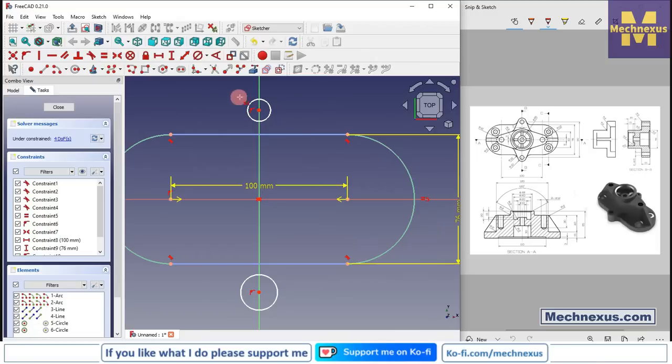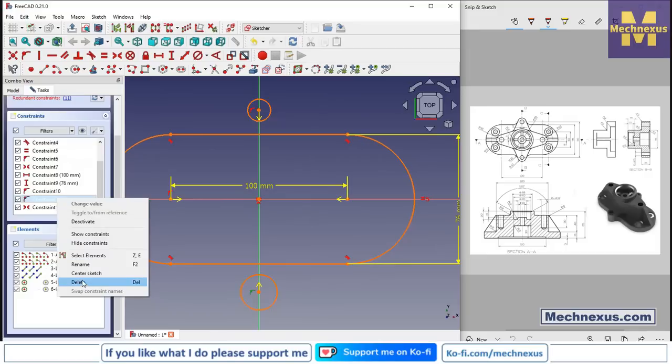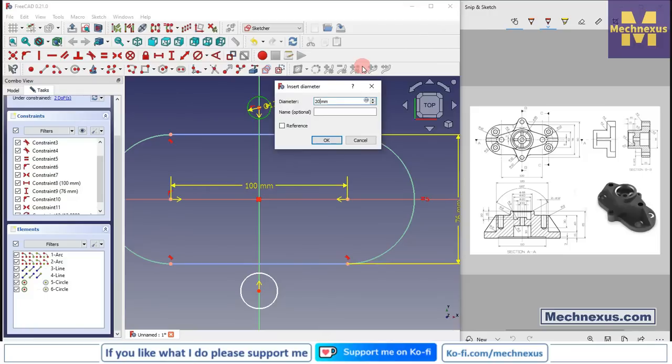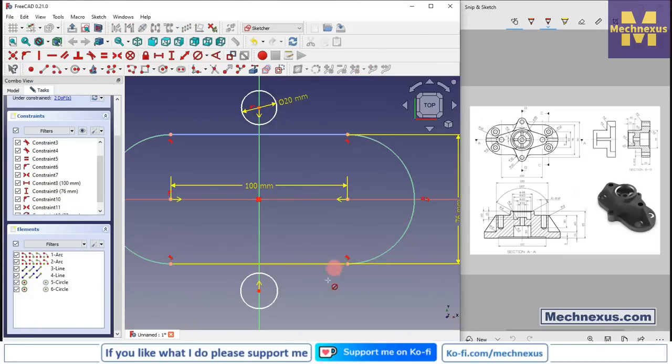So we will use the symmetricity. Select this point and this axis, and here we will delete this conflict constraint, and we will select diameter and provide it 20 mm, and we will select this and this and this and make it equal,